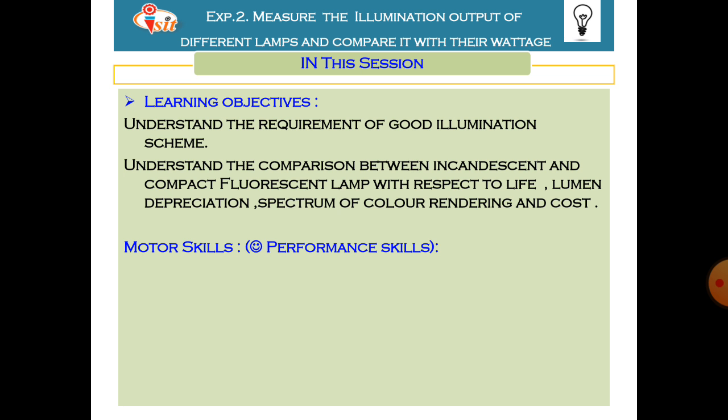As more efficient lamps are there, the lamp life also increases. If the lumen output is very low, then depreciation is very high. So there is a need to compare the lumen output and depreciation of various light fittings. According to that we can select the type of lamps for a particular application.